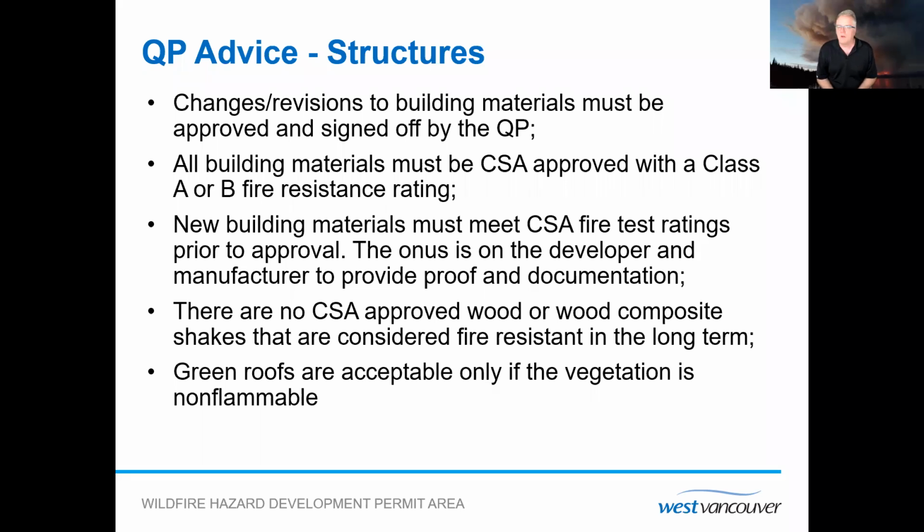From my knowledge, there are no CSA approved wood or wood composite shakes that are considered fire resistant in the long term. There are some manufacturers that advertise that they are manufacturing a fire resistant shake. Generally, they fill the pores of the wood with resin. And yes, you can put a torch to it when it's new and it will not light on fire. But as that resin breaks down over time, the resistance of the material degrades, and at some point will in fact burn.